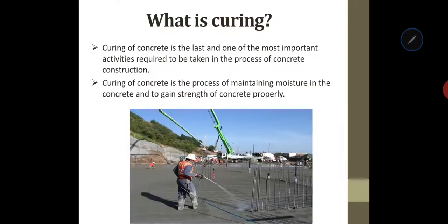So what is curing? Curing is important in concrete mix because we need the concrete to set to the designed strength. Curing of concrete is the process of maintaining moisture in the concrete. The objective of it is to gain the strength of concrete properly.